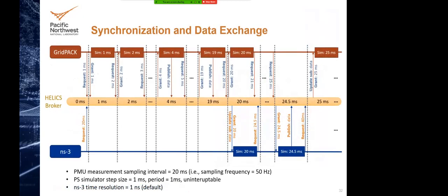So with this slide, I'd like to show a simple example of the synchronization and data exchange in this project. Here we have GridPACK as a power system simulator, which has a fixed step size. In this example, I show it as a 1 millisecond step size. And ns-3 is a discrete event simulator. It does not have a fixed step size, so as you can see, it can be granted different sizes of steps.